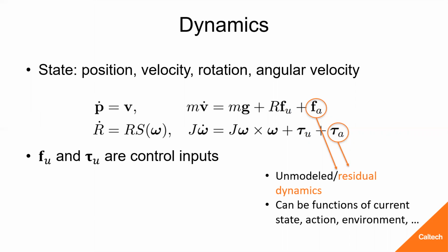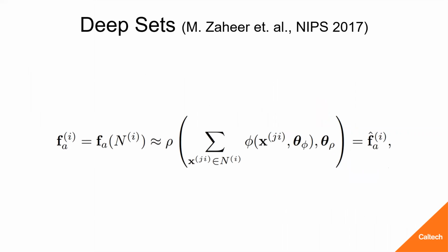So that we don't really know. There are no good models. And so again, we use the deep sets, and we just assume that it should be permutation invariant because all the quadrotors are identical. Here, our set of neighbors is basically the relative state between robots. What we used was the relative position and relative velocity between robots that are somewhat nearby.